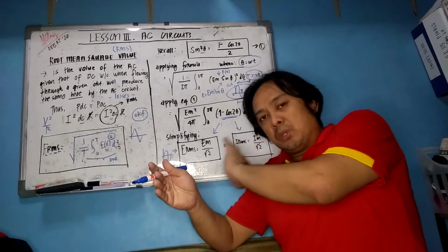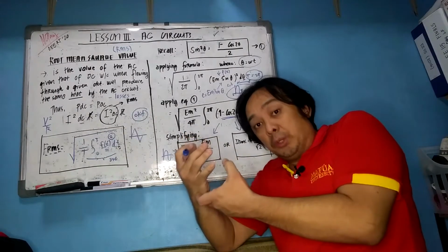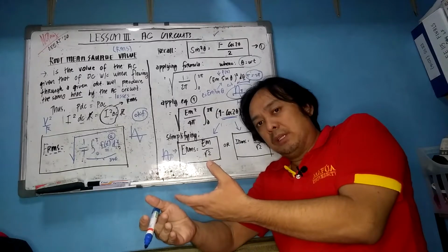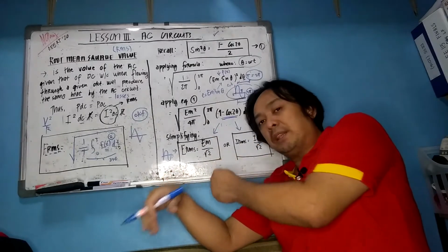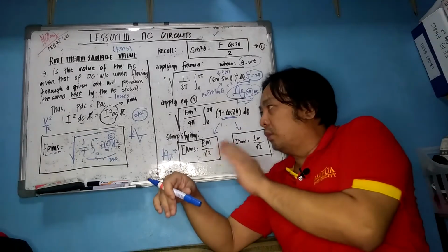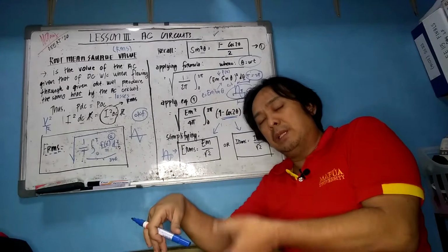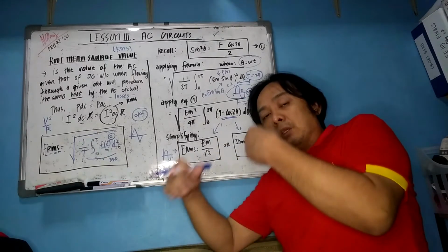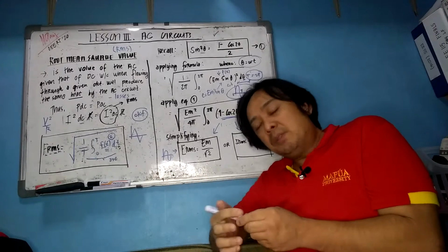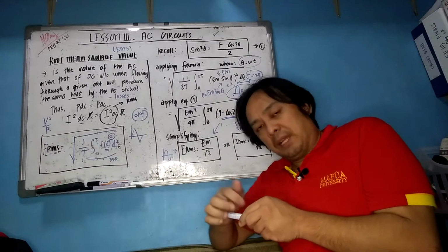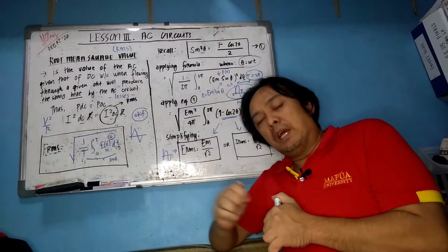Now, these root mean square values are the values that you see on your meters, like your voltmeters. The value of the current and the voltage there is represented by a root mean square. And you already know what root mean square is about. Root mean square again is the value of an AC signal that is equal to the DC signal that will produce the same heat dissipated on the same circuit at the same time. Now, we can go forward to the other fundamentals.